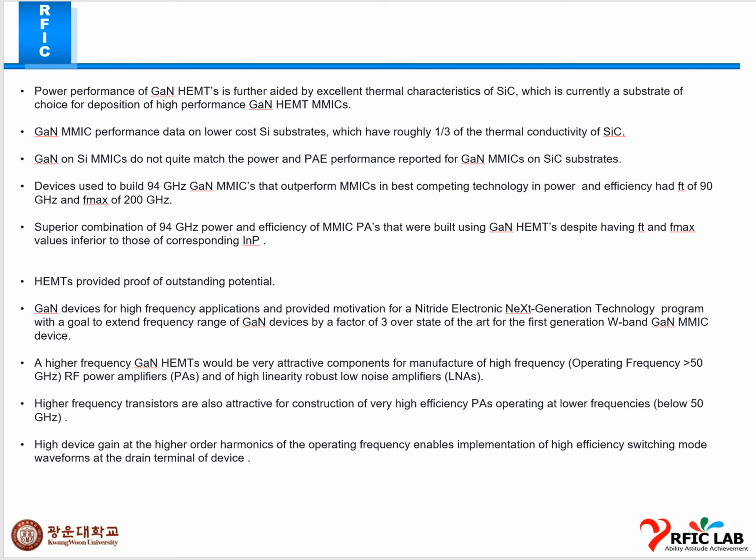GaN HEMT performance is further aided by the thermal characteristics of the substrate, from the choice of deposition of high performance GaN HEMT MMIC. This performance data is for lower cost Si substrate, which has roughly 1/3 of the thermal conductivity of SiC, and GaN on Si MMICs do not quite match the power and PAE performance of GaN on SiC. The GaN MMIC on Si substrate outperforms the best competing technology in power and efficiency,